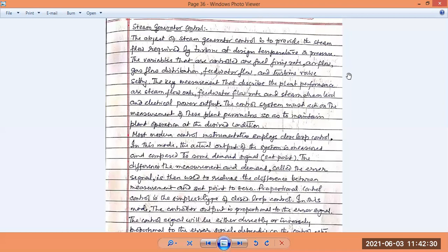Actually, the same water is being circulated throughout the system again and again, but you can never recover 100% of the water and convert it again to steam. You have to feed a certain amount of water itself. So this flow rate throughout the system is also important to know, because you have to know how much you have to add to the feed water itself.